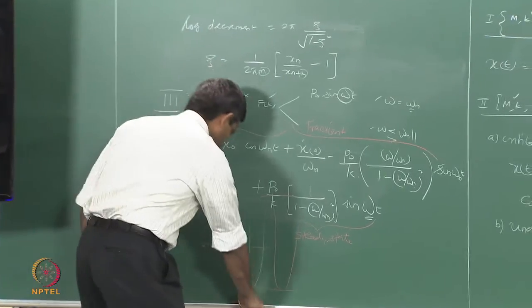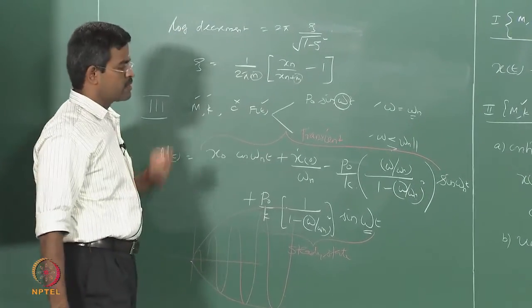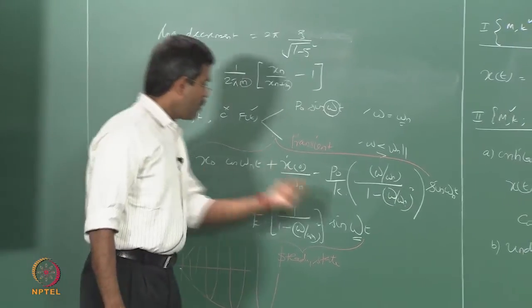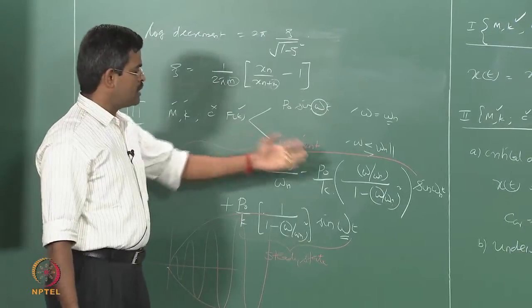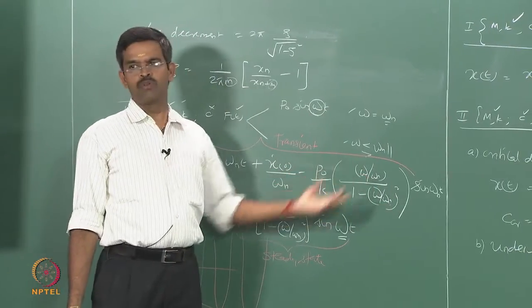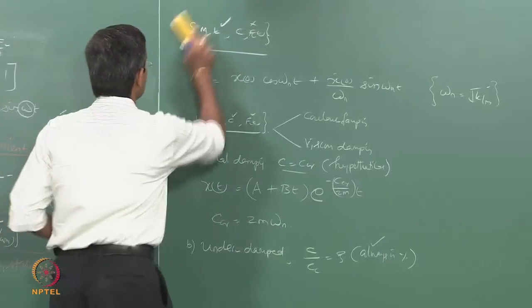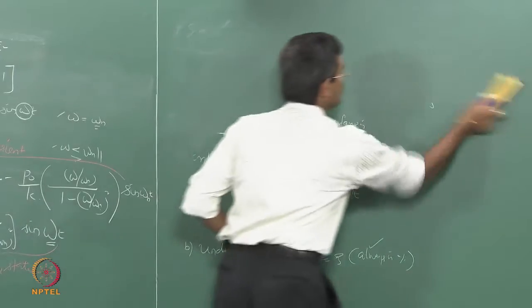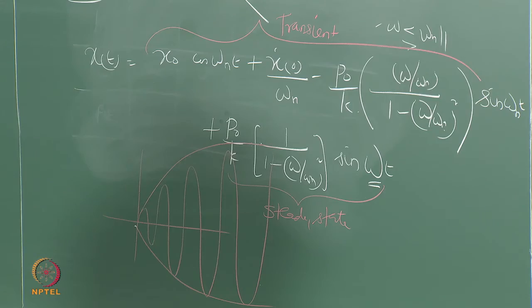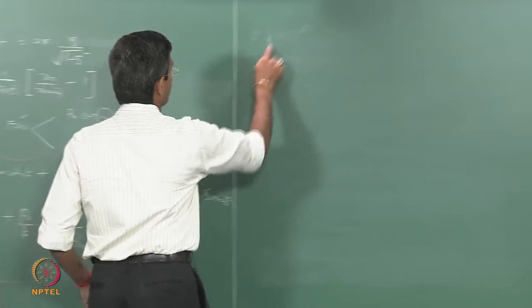Okay. This is what we have discussed as far as x of t is concerned. Now, when omega equals omega n, you will obviously see the denominator becomes 0. You cannot use the same solution back again. So, we said the particular integral is different. Therefore, we gave an equation which ultimately results in what is called the deformation response factor RD. So, we made it simplified to understand